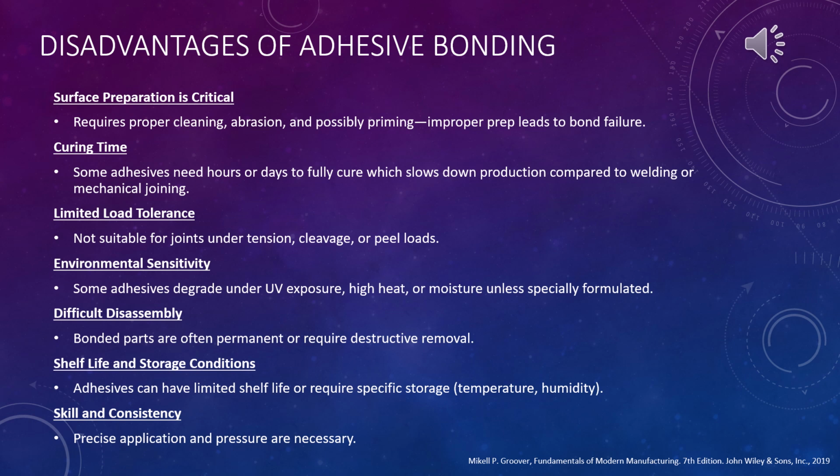Number 2 is curing time. Some adhesives need hours or days to fully cure, which slows down production compared to welding or mechanical joining. During this time, parts may need to be clamped or held in place, which can slow production lines. There are fast-curing adhesives out there, but many compromise on strength or temperature resistance.